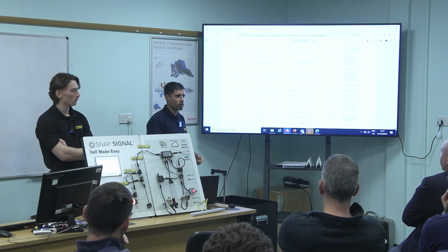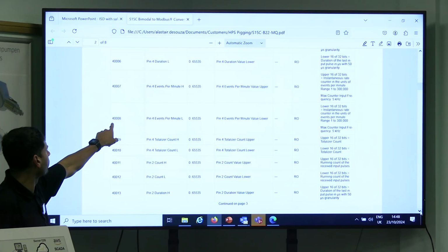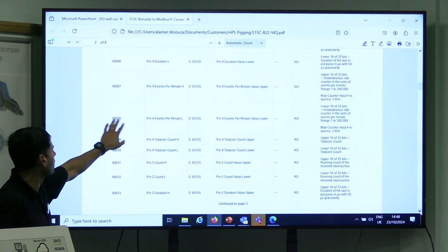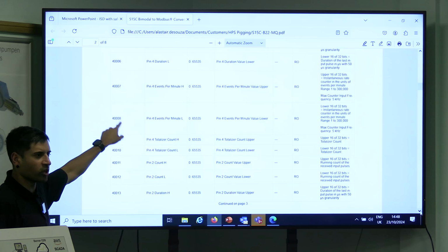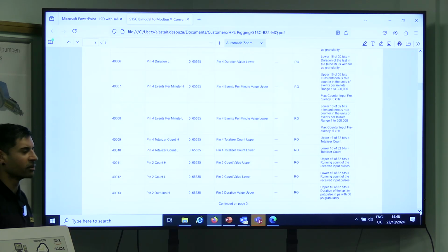But what it is, you then read that value from the controller in our software: read Modbus register 8. It will be 8 because everything's done via holding register. So we leave off the 40 and just say we want to look at slave ID 1, register 8, and that's how you get the value in, really.